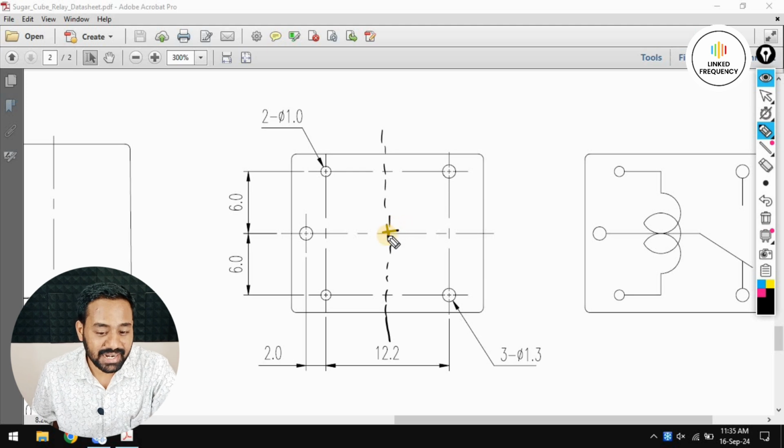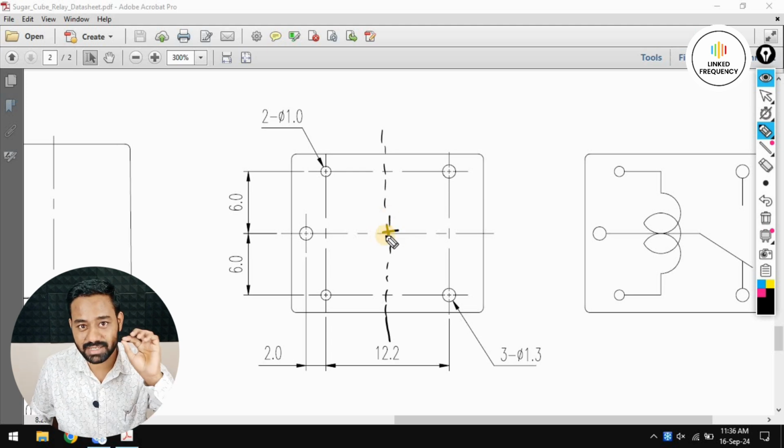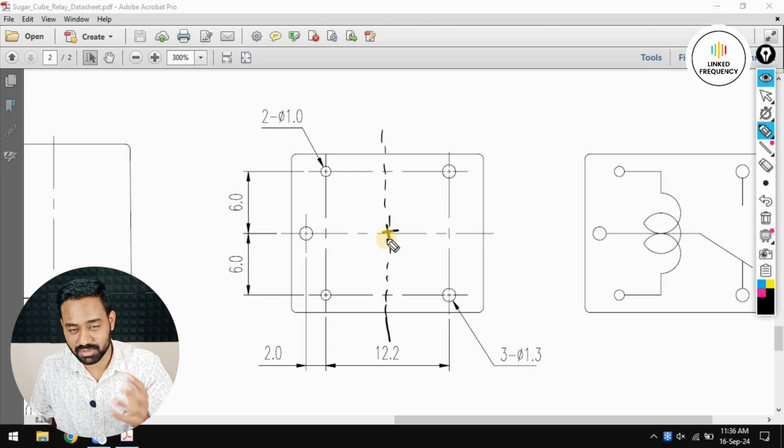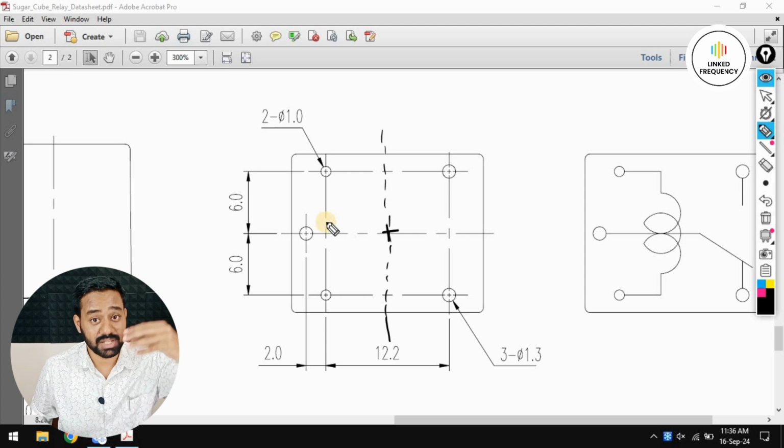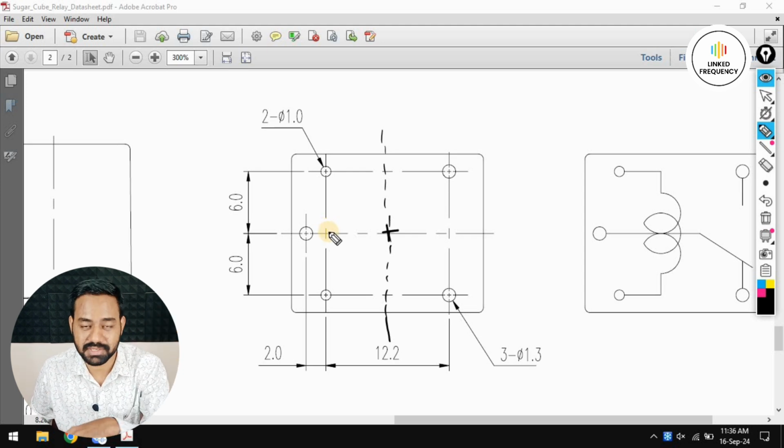It's not necessary that we anchor this entire footprint at the middle itself. If you can do that, that's amazing, and that's the professional way. But it is not necessary. It is like overkill actually. Instead, we can focus on the dimensions properly, so that when you manufacture this PCB, your component will sit on that particular PCB and be easily solderable. That is more important. IPC standards are more important.